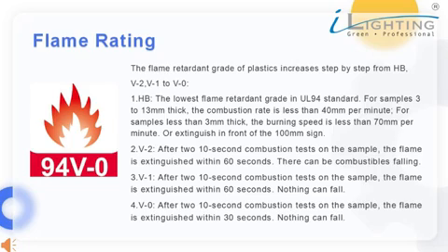2. V2. After 10-second combustion tests on the sample, the flame is extinguished within 60 seconds. There can be combustibles falling. 3. V1. After 10-second combustion tests on the sample, the flame is extinguished within 60 seconds. Nothing can fall. 4. V0. After 10-second combustion tests on the sample, the flame is extinguished within 30 seconds.